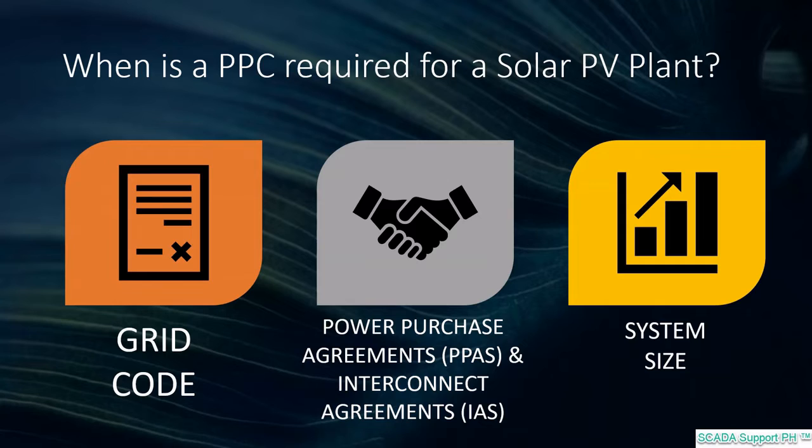Even if these rules vary a lot between countries, essential functions need to be handled whenever a solar PV power plant is integrated into the grid, such as active and reactive power, as well as voltage and frequency regulations. For grid-tied power plants, it has now become a necessity to use solutions based on power plant controllers because of the ease they offer in running the power plant.